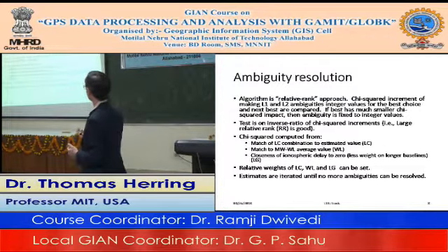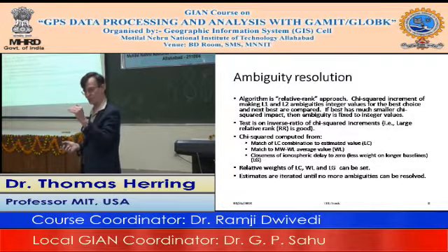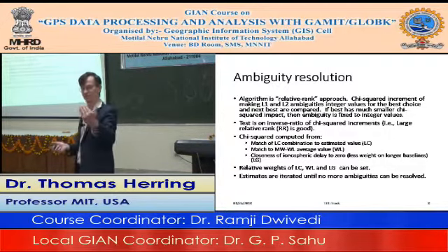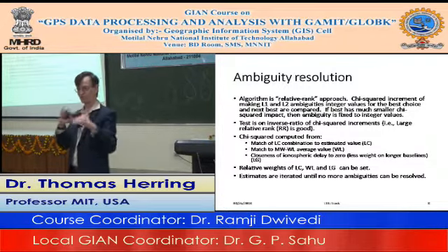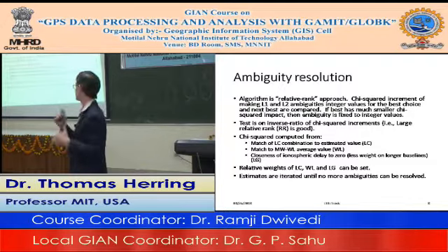So it does that, and it looks at, as I said, this relative rank RR, and it's the chi-squared from the match to the LC combination, the Melbourne-Wübbena wide lane, and the ionospheric constraint. Now again, one of the tuning things you can do is set the relative weights between these as to how important they are. So again, the Melbourne-Wübbena wide lane, if the instrument's working well, generally we keep at unit weight. But we do have instruments where the pseudo ranges aren't being measured very well, and so we have systematics there.